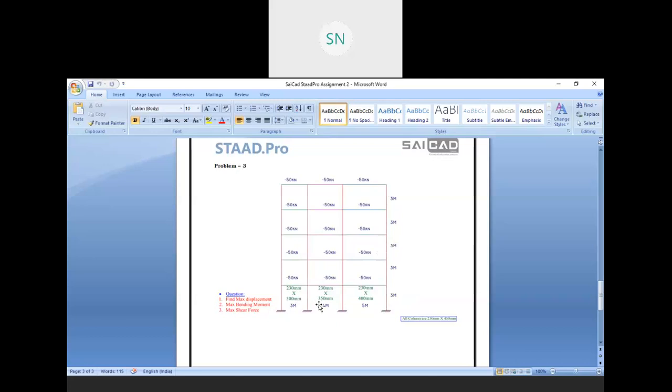Either we can draw it manually with our modeling tools like the graphical method or using a command file. Or we can use our structure wizard also. So try to practice with structure wizard and also keep your hand on both methods, command file and graphical method, because for modeling any complex structure we need the help of all these three things.